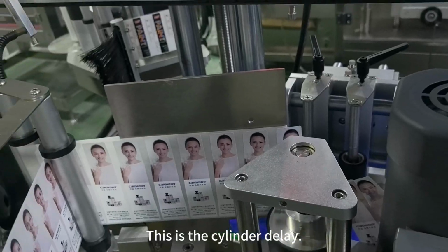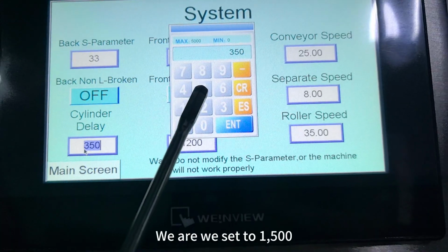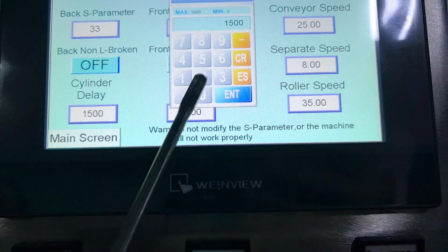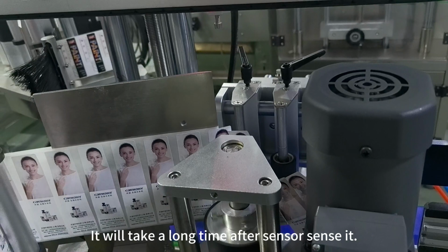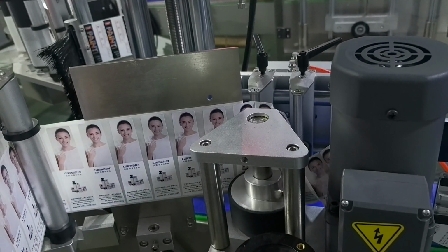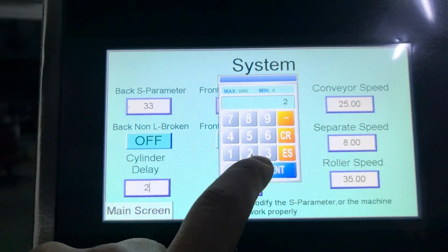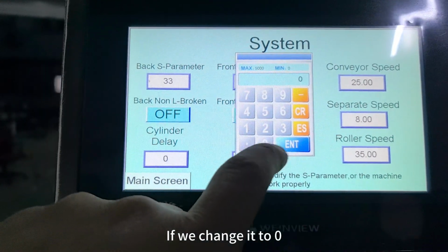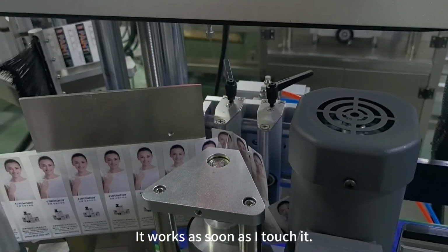This is the cylinder delay. The delay was 350. We reset it to 1,500. Let's feel it. It takes a long time after the sensor senses it. If we change it to 0, look. It works as soon as I touch it.